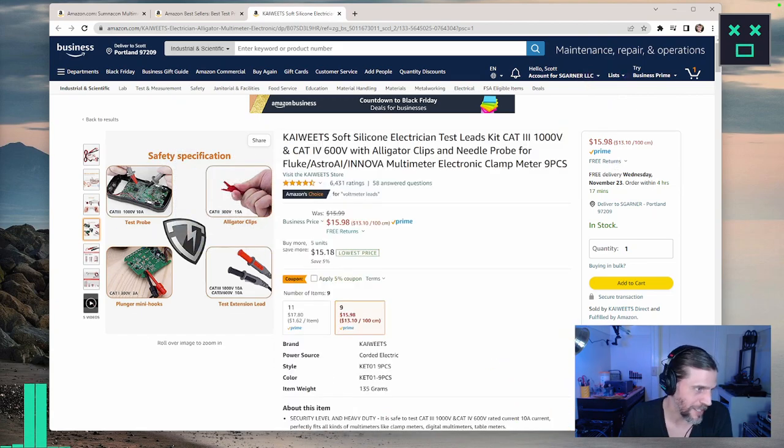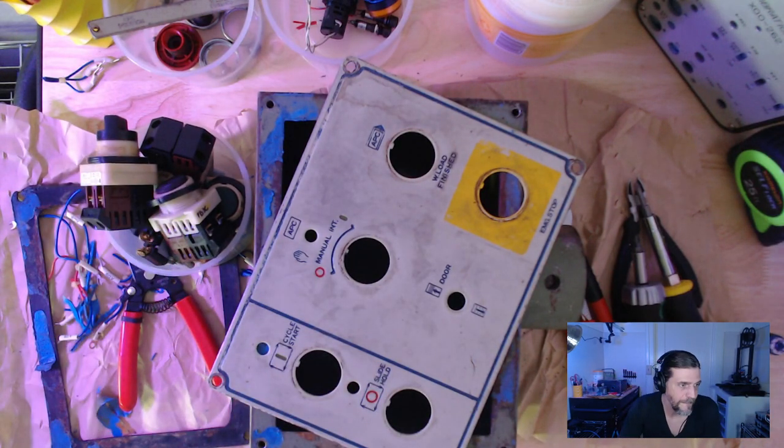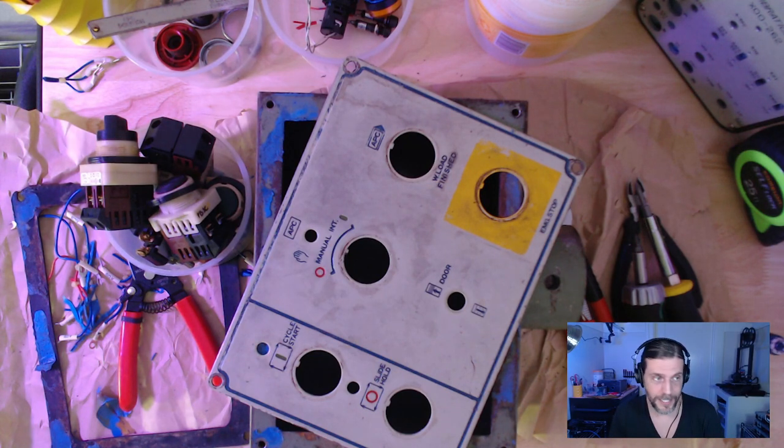So basically what we did is we took apart this weird thing over here. And I want to... Oh, sorry about that echo. I want to turn it into an Internet of Things device. And so looking at how to do that seems pretty straightforward for the most part. I think we just stick an ESP32 in there. One issue is the voltage of the little lamps in it. They are 24 volts, so I'm just looking for silly ways to get from 12 volts to 24 volts, and then suddenly I got distracted by